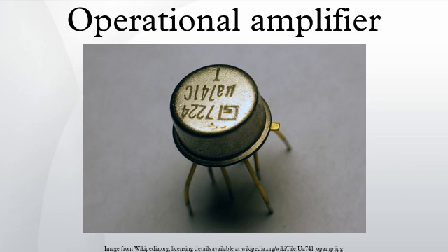The non-inverting input of the operational amplifier needs a path for DC to ground. If the signal source does not supply a DC path, or if that source requires a given load impedance, then the circuit will require another resistor from the non-inverting input to ground. When the operational amplifier's input bias currents are significant, then the DC source resistances driving the inputs should be balanced. The ideal value for the feedback resistors will be such that the two resistances in parallel roughly equal the resistance to ground at the non-inverting input pin. That ideal value assumes the bias currents are well matched, which may not be true for all op-amps.